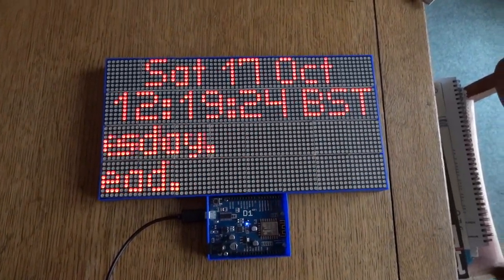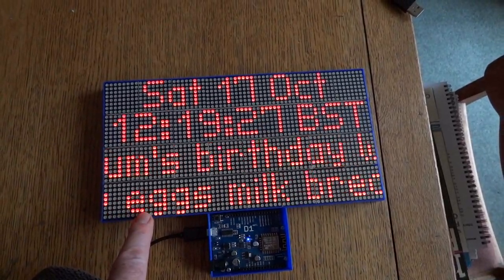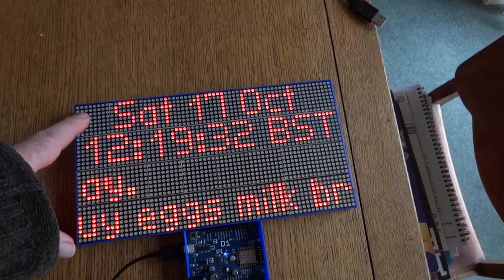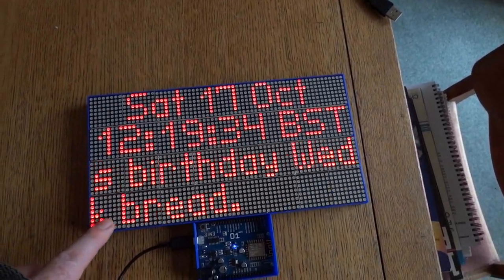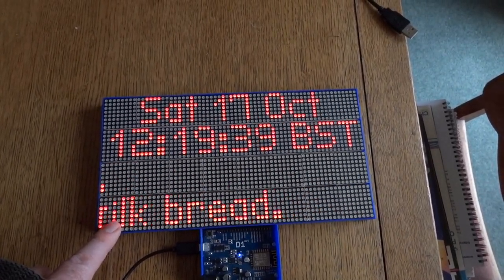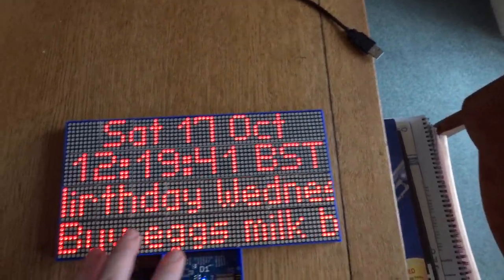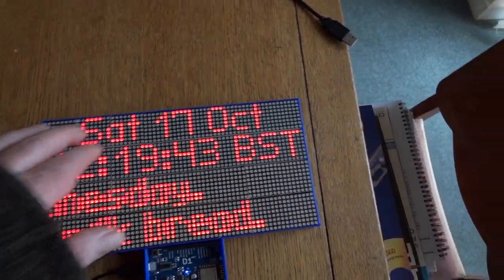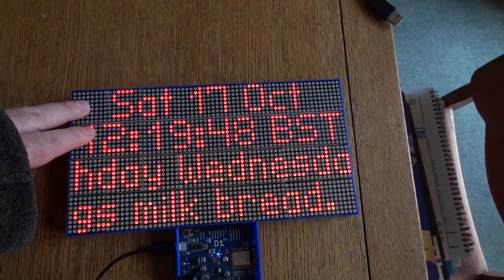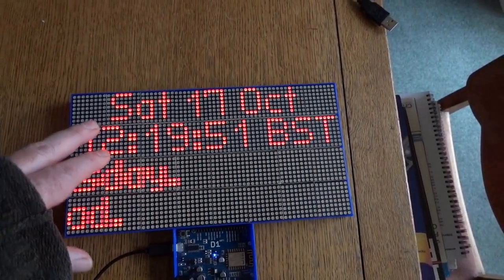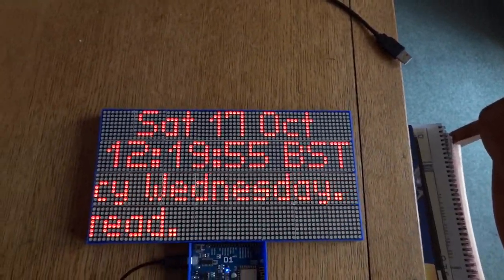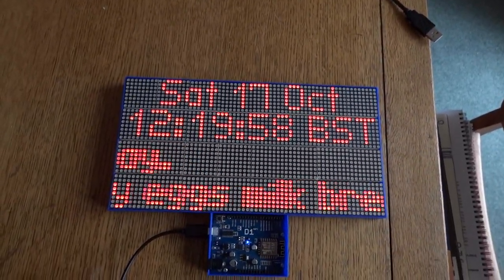And the way I've done the driver for these things is you can sort of specify windows. I've specified 4 windows, which equate to the 4 rows at the moment, but you could do more than that if you wanted to. So you could split a row up into 2. The rows can straddle the physical rows of the displays. They're pixel based, so you might have a block here and another one here. It doesn't have to be per row.